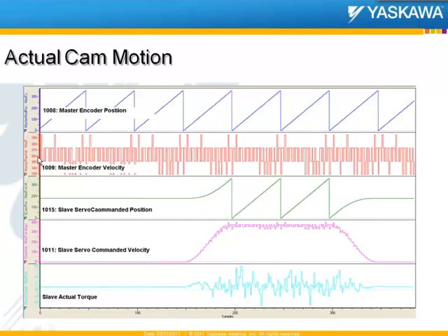units per second, but what I'm seeing in reality is a lot of spikes, a lot of hills and crests and valleys and all kinds of jagged data coming through. And this is an example where I'm using an external encoder with a resolution of 8192 counts per rev, and you can see the velocity is going up and down.